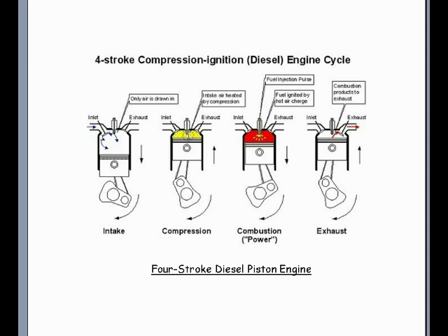The typical compression ratios of gasoline piston engines is around 10-to-1 compression ratio. But on the diesel piston engine, the typical compression ratios are 23-to-1. So with that type of extreme compression of the air, the temperature will rise to ignition temperatures. Only on startup there will be assistance with a glow plug to help heat the air with the heat of air compression. But instead of a spark at before top dead center, there will be fuel injection of diesel fuel.